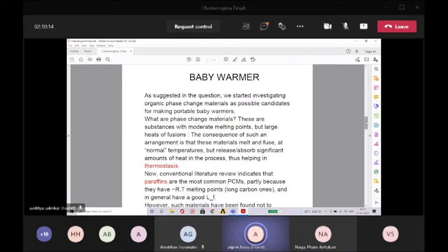So that is the basic concept of nucleation. Hysteresis in this context will arise because, as I said, small nuclei of solid PCM will be left around, and when the liquid tries to freeze again, it will have a relatively easier time doing so, because it already has a certain threshold of nuclei available upon which it can condense. So that will be the cause of hysteresis. Every time, the freezing process becomes slightly easier than in the earlier cycle.